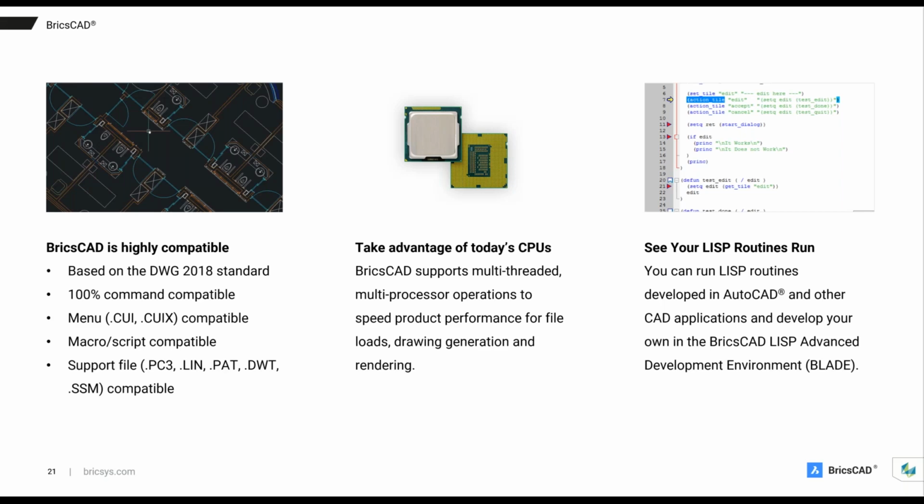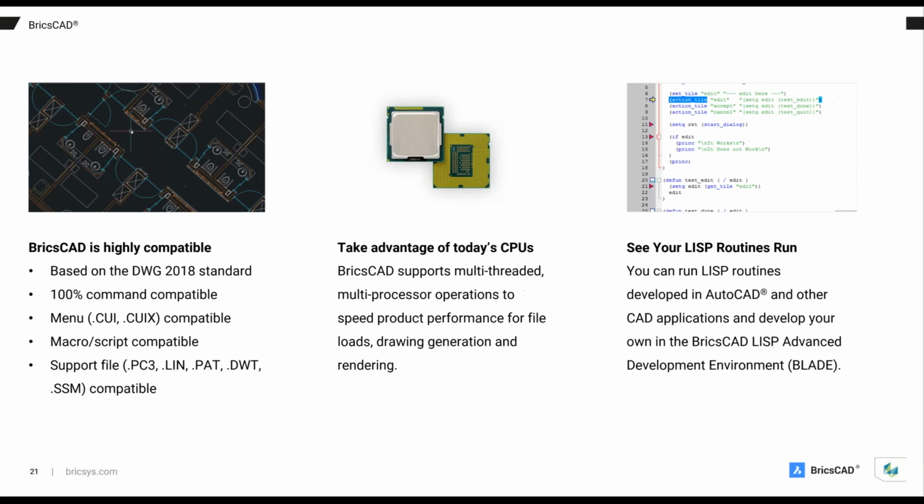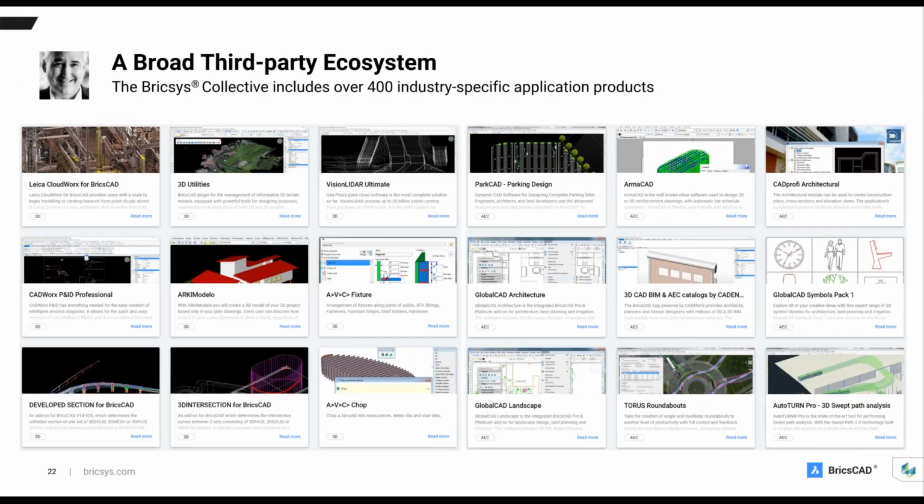But wait, there's more. I couldn't help it, guys. I just had to say that. BricsCAD supports Lisp, .NET, and what we call our BRX development environment. Now, BRX is the BricsCAD runtime extension. It's code compatible with Autodesk's ARX development system.